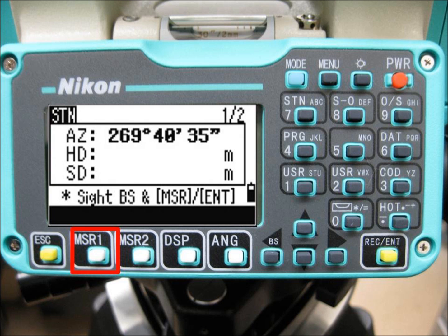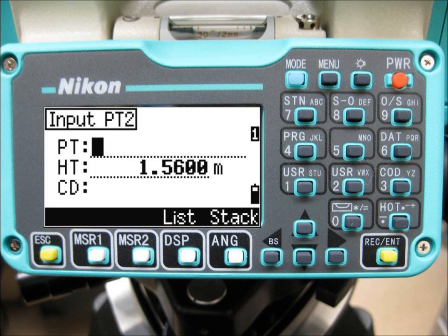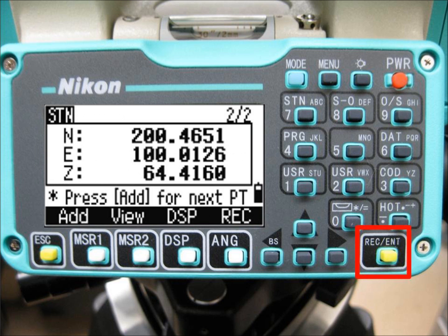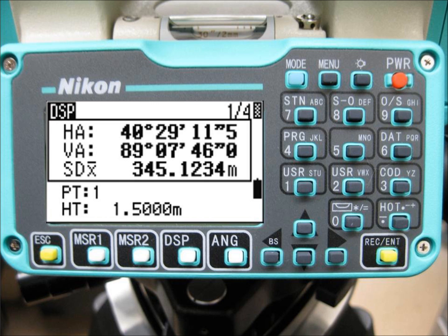When the measurement is complete, you'll be prompted to enter in a new control point. Enter in the name of the second control point, have your rod person move to that one, and then take another measurement similar to what you did with the first control point. When you're finished with the second measurement, it should display the coordinates of the total station. Hit Enter to record the coordinates, and then hit Escape to return back to the measurement screen. You're now ready to start taking topo shots.